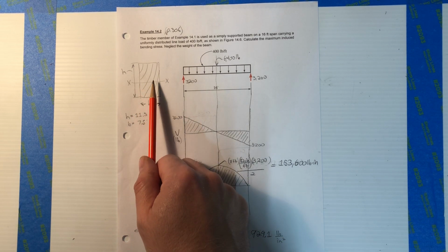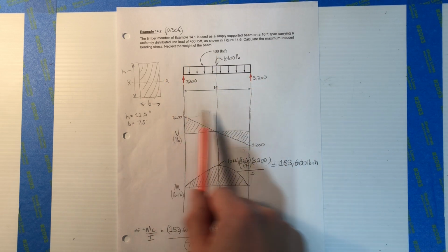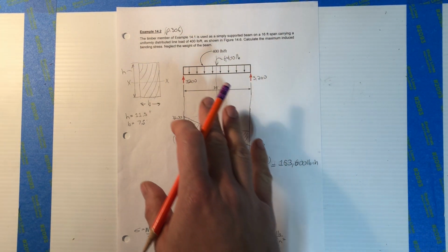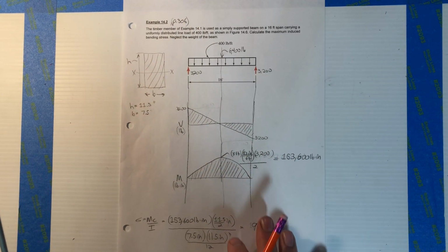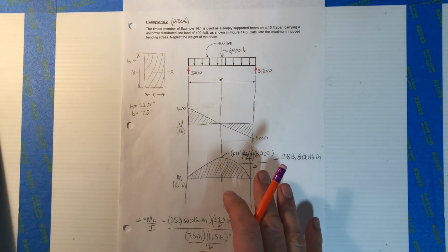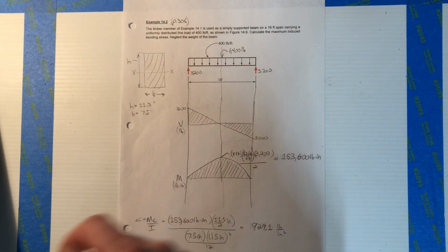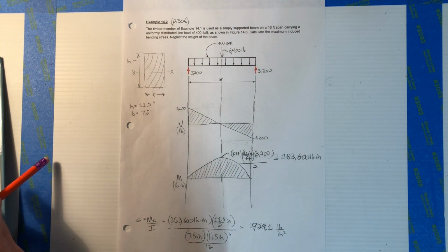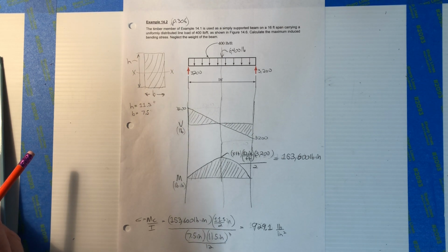If you think about it, this is a case right from the handout I gave you or the back of the book, right? So this is going to be, instead of doing a shear moment diagram, what we could have done is we could draw it like I did with all the steps, or you can use Appendix H in your book, right?